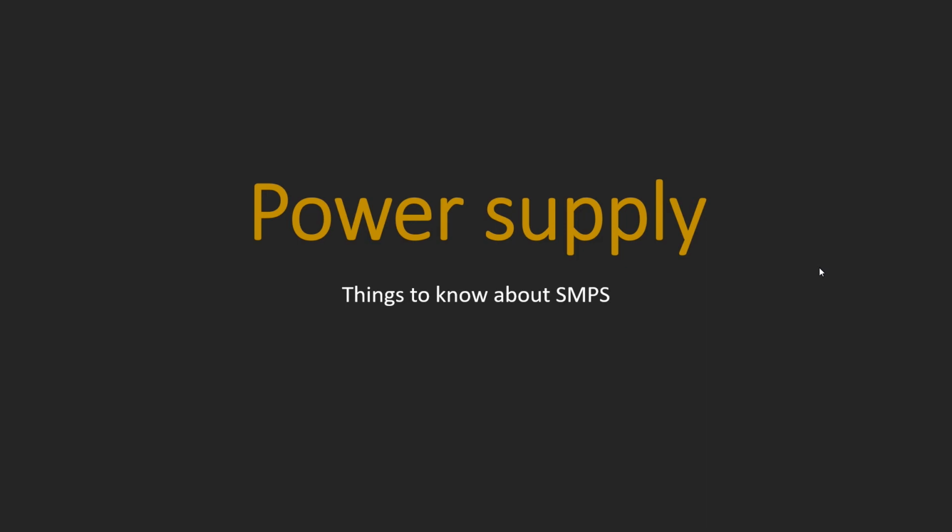Another important component for a great audio amplifier is a power supply. In reality, power supply costs are higher than the amplifier stage. Class D power amplifiers are sensitive to power supply voltage fluctuation, therefore classical mains transformer power supplies don't suit for Class D amplifiers. You need a regulated low noise switching mode power supply capable of working with almost no load to max load conditions. There is fundamental difference between industrial power supply requirements and audio amplifier requirements.